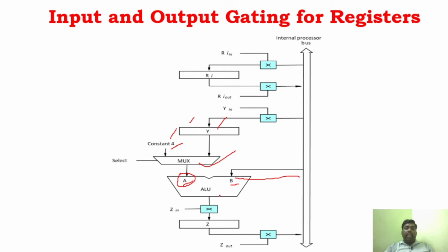Then the ALU will perform that operation and store the result in the temporary register, correct? From the temporary register it is moved to the internal bus, and from here it can be moved to the destination, okay? Now I have explained this very clearly. Before going to the instructions, you have to understand R1, R2 and R3, correct?